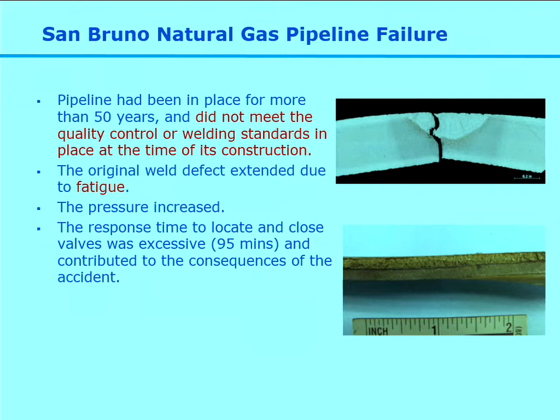Right, ground movement. I mentioned the reason ground movement is important is because it can obviously apply massive loads to the pipeline. And this is an example of a pipeline where the failure didn't actually result in a release of gas, but it did fail because of the curvature damage which occurred.